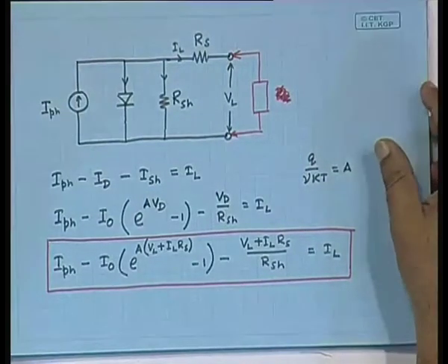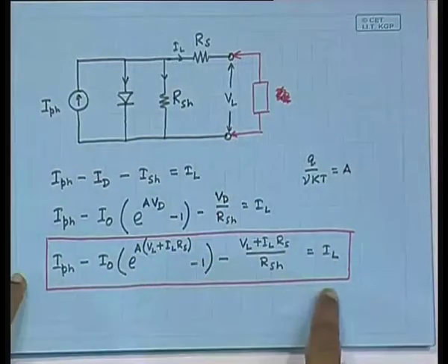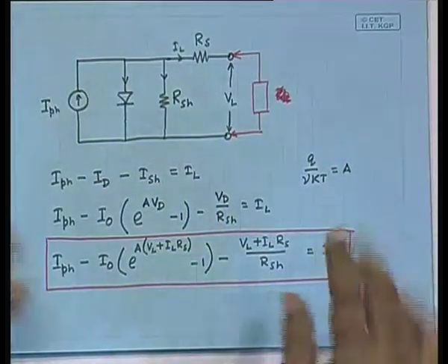If it is fixed, they are linearly related. The idea was, the linear relationship was that there is a source fixed, you have got a resistance that is varying. So, the current varies linearly with the resistance, but here the source is not fixed. As a result, the relationship between VL and IL will have a specific property given by this equation. Let us see what this specific property is.